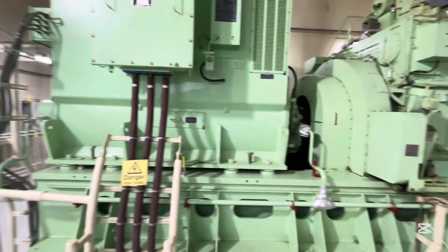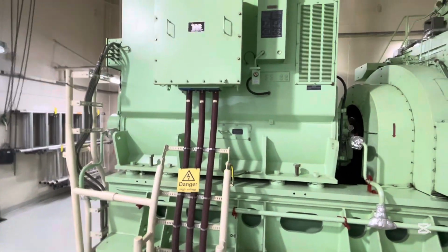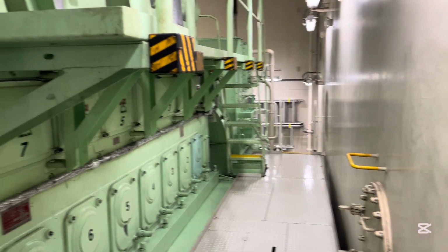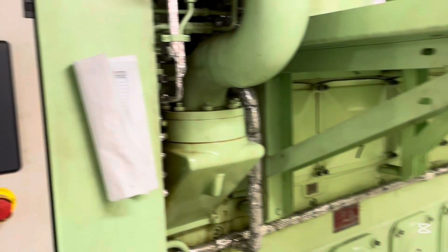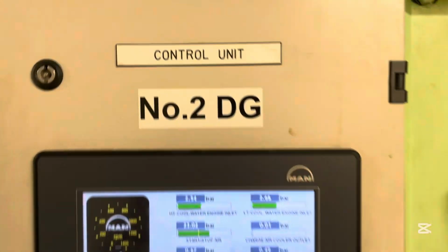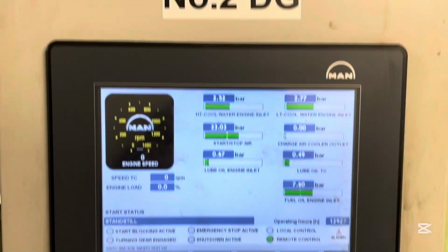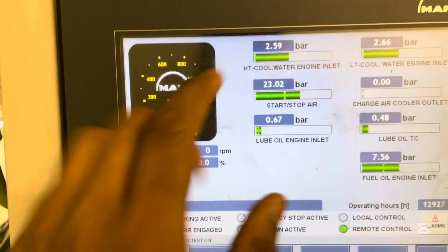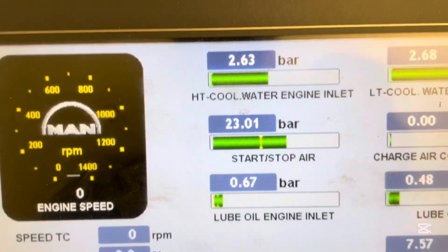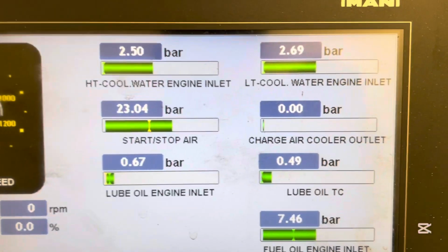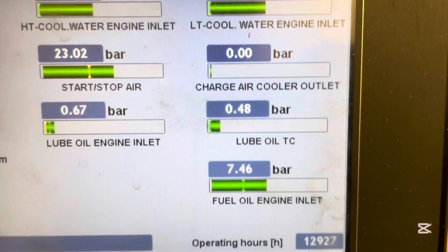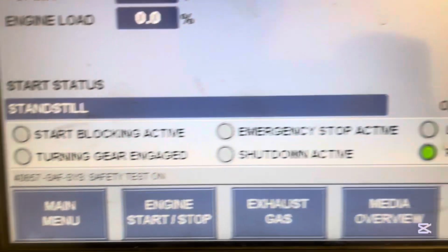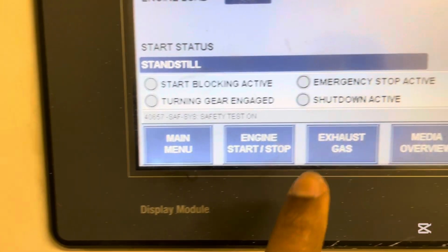We'll just focus on the engine and its control system, okay. So far we understand that there are three places from where we can actually control the auxiliary engine from the ECR: the control panel, the CAMs, and the PMS. And the fourth and final one is locally. Those are remotely controllable, and this is from the engine side itself. We can control the engine. So this engine control system is present on the engine side itself.